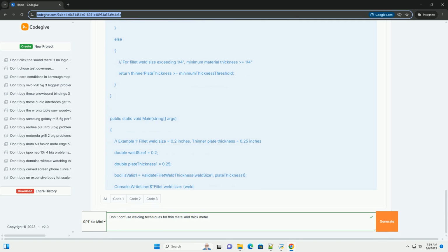8. Code considerations. Welding codes are crucial for ensuring structural integrity and safety, especially in critical applications like pressure vessels, bridges, and buildings. Codes dictate material requirements, welding procedures, and inspection standards. AWS, American Welding Society: a widely used code for structural welding, pipe welding, and other applications. AWS codes specify requirements for welding processes, filler metals, welder qualification, and inspection.